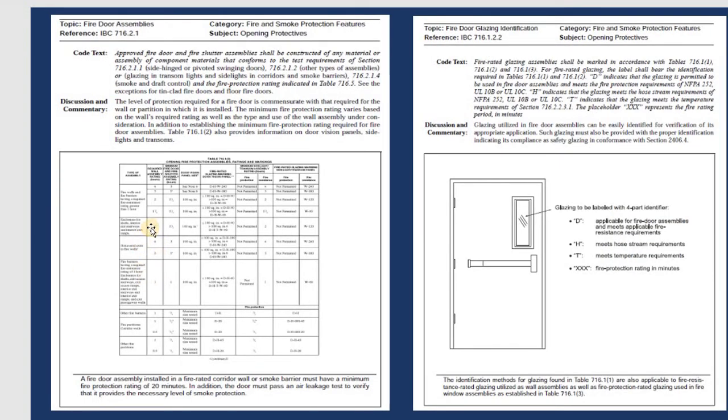This is the table to let you know that for the fire protection assembly they have the testing material you need to follow, what construction group, and how many hours of fire rating. If you have a sprinkler or not, it changes things. Usually if you have the sprinkler system, you can reduce the hours from the regular fire rating. This is one of the doors.